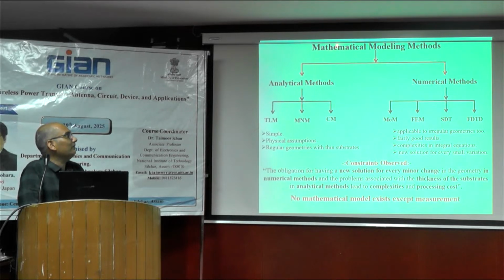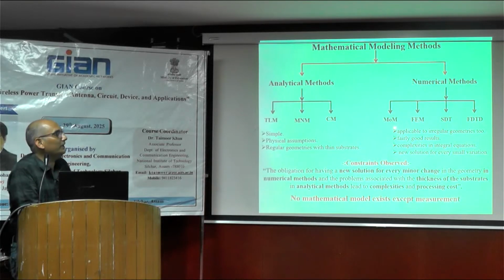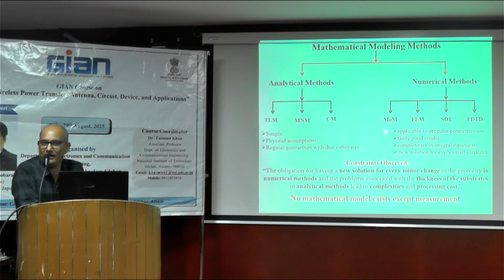Now, the traditional ways of modeling antennas available in the literature are the transmission line model, multiport network, and cavity model also. Okay, those are analytical methods. Then numerical methods, say the method of moments, finite element method, spectral domain technique, finite difference time domain. Each one has specific applications and specific advantages as well as drawbacks, because we need to drive the need for machine learning incorporation in the existing modeling approach. That's why some problems based on the analytical methods are highlighted here.